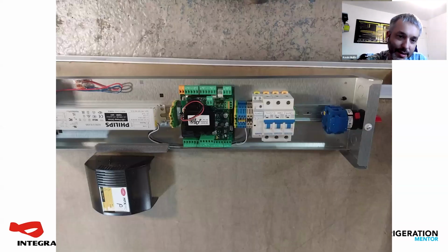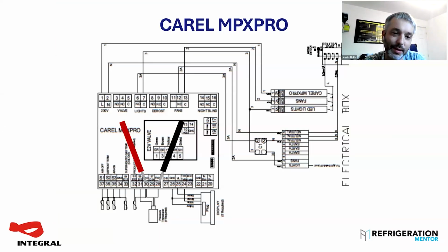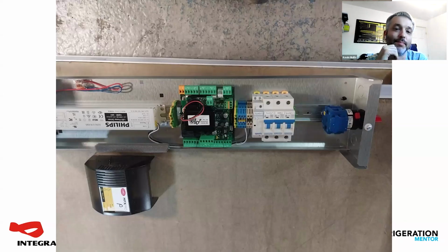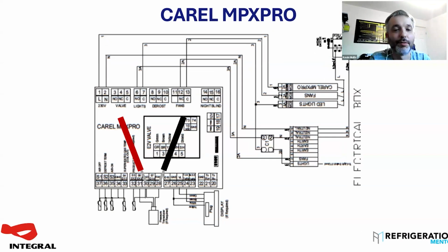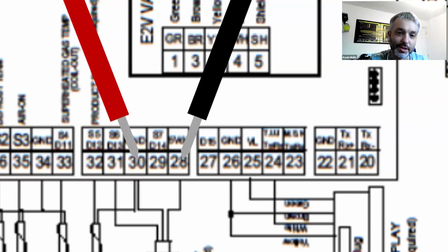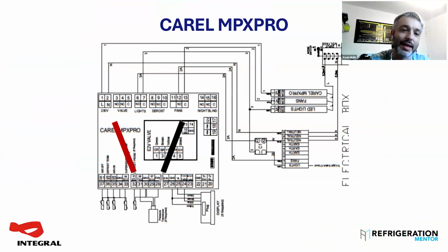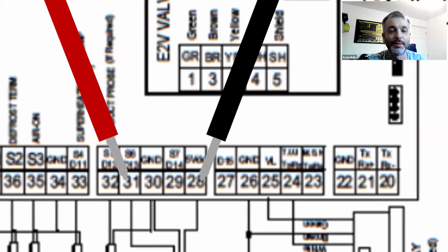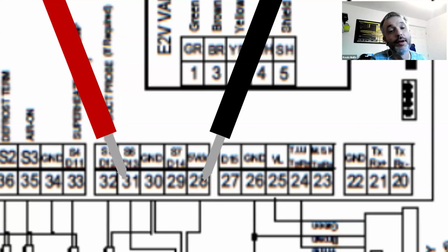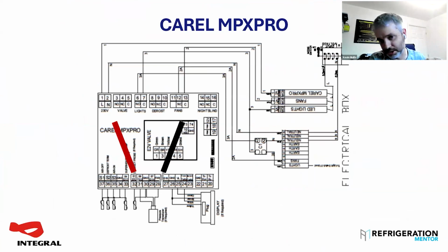Trevor's just highlighted on their transducer. So again, it's the same type of transducer, 5-volt ratiometric that you would use on the Danfoss. That's your terminals for checking the supply out to the transducer. It comes back on S6 on Carel for checking the voltage return. As I said earlier, with Carel, if you're daisy chaining it to an island, you have to use the right transducer.